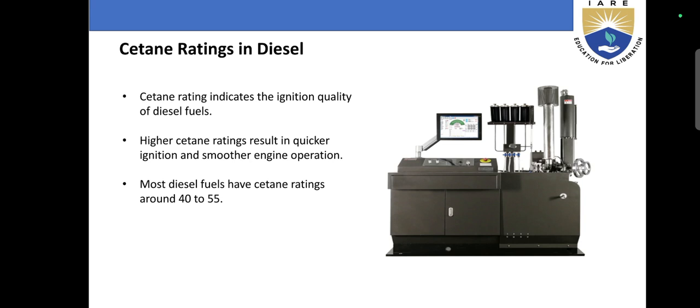Next, cetane ratings in diesel. Cetane rating indicates the ignition quality of diesel fuels. High cetane ratings result in quicker ignition and smoother engine operation. Most diesel fuels have cetane ratings around 40 to 55.